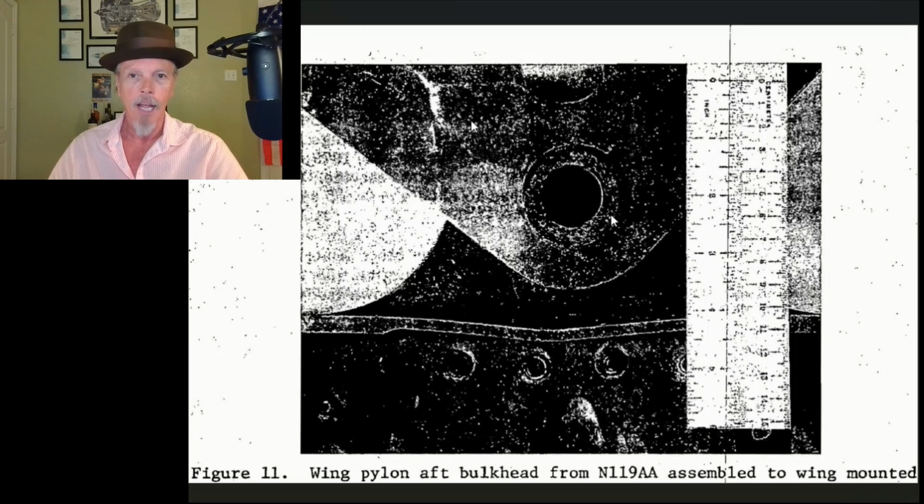Now this is still together, but if we're looking at this, we're seeing the bottom of this is about here. So we've got 1 inch. Maybe, I mean, you're talking 1.5 inches from where the work that they're having to perform, once this is all removed, the work they're having to perform to where the damage occurred, an inch, inch and a half. And you can see from the service bulletin, it said to inspect the bulkhead and the spherical bearing and all this for damage around there. So I don't see how they could miss it if this occurred on removal.